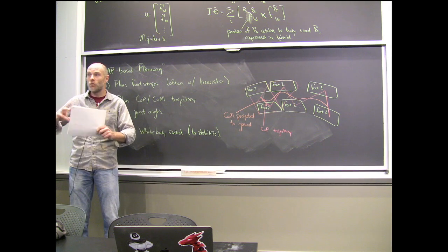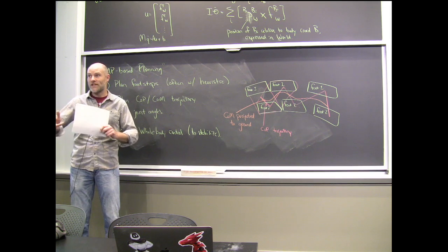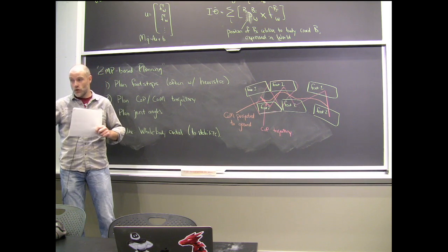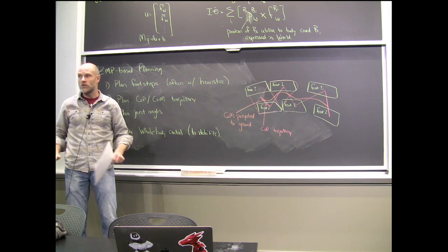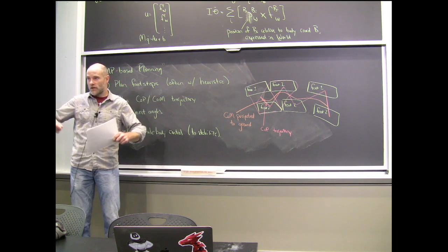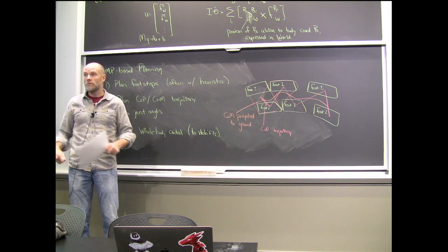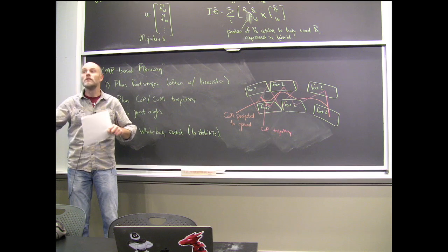If I had to guess at a high level, what are they doing? I think they've got libraries of trajectories of the centroidal dynamics. They find the closest one to what they're about to execute, and I suspect they do have a choice of which step they're going to step on in which order and stuff like that. And they pull it from the library, and they talk a lot about online model predictive control. So they're constantly replanning those trajectories from that initial library on the fly.